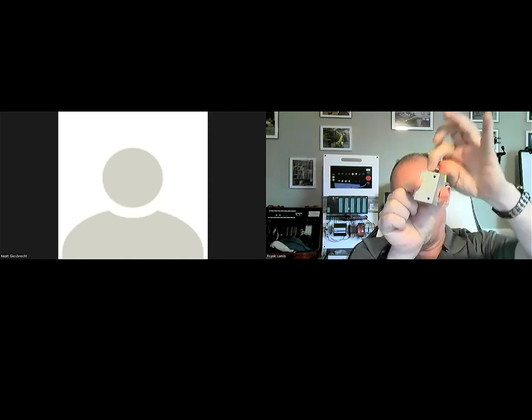Here's one of the typical cylinders that I showed in the cutaway before. It's got a couple ports here, and you'll notice since there's plugs in the ports, I can't pull this thing out very easily, right? Because air has to escape out of the ports. Here is a small version of the same thing. You can see mounting holes here on the back. You can see the two ports here on the front. If I were to plug one of the ports, then I can't pull this out. But if I let go of the port, then it moves. So plug the port, and it kind of bounces back, let it go.